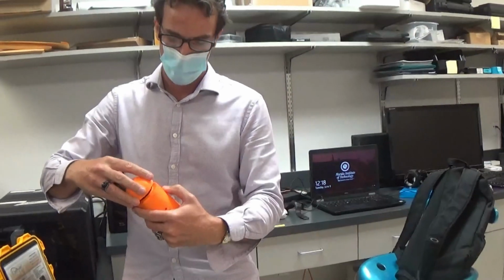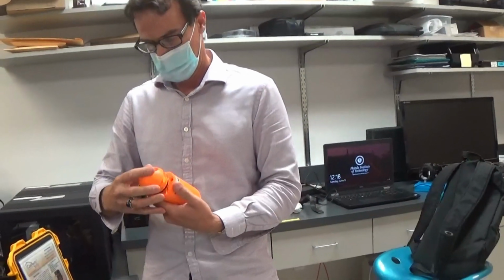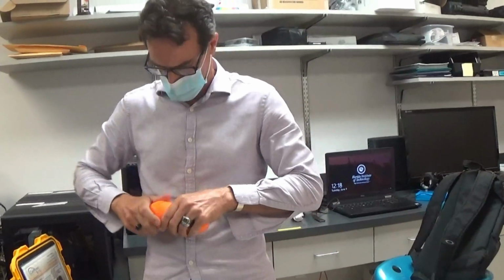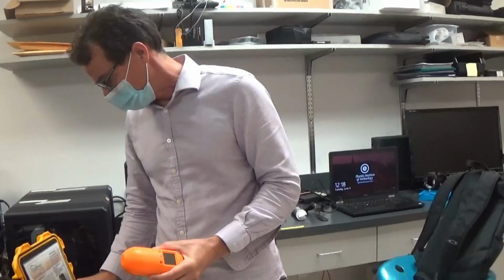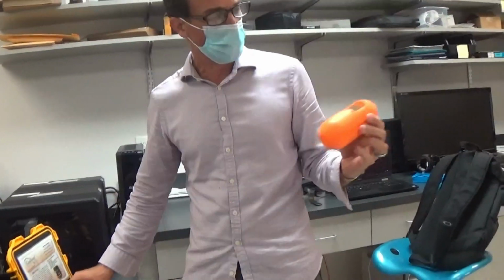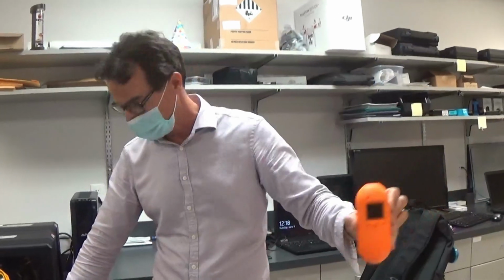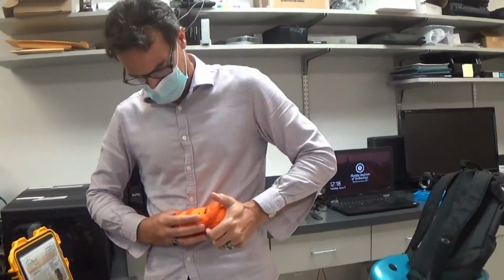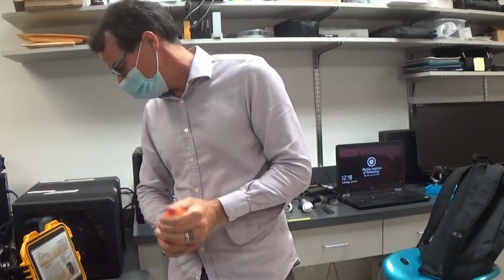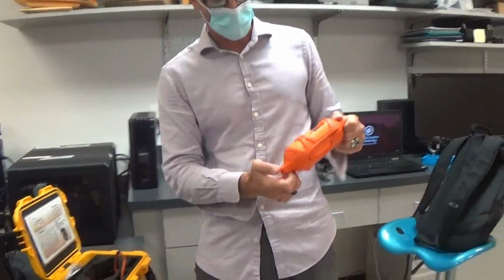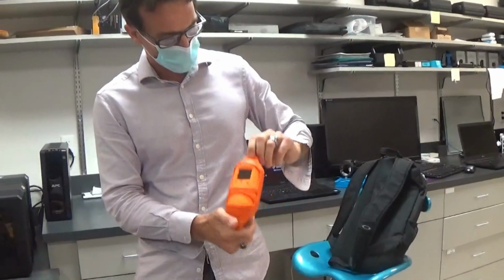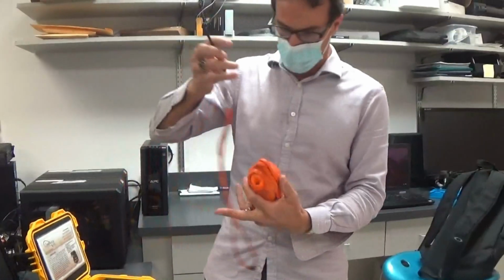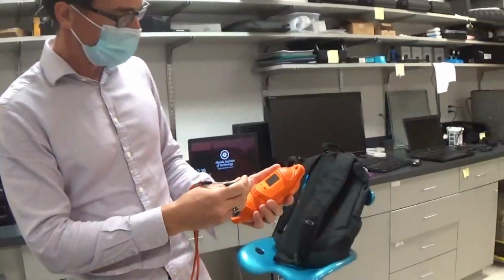And then we want to line it back up and twist it back on. Okay, so this whole unit gets thrown into the water. Of course, clearly you don't just want to chunk it into the water because you have to be able to retrieve it, so that's why we have this nice sleeve. What you'll do is you clip a weight onto the bottom side of this, and you clip the top side to some line, and I've sometimes seen this has inboard GPS.